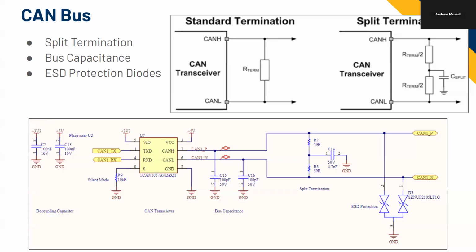In reality, they're more complicated than that. Even in the forward direction, you'll have a voltage drop over the diode when it conducts. So the first diode allows current to go through, and the second reverse bias diode stops that. And then when the voltage gets higher than the reverse breakdown voltage of that diode, it will start conducting in the reverse direction.